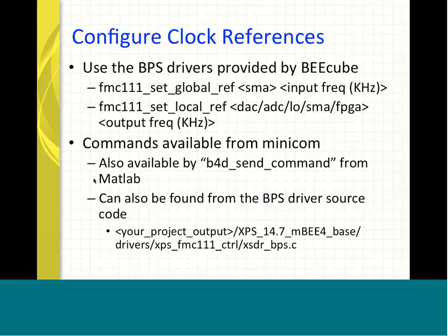As people who have already used the FMC111 or miniBEE SDR know, you can use the B4D send command from MATLAB to change these frequencies. So if you don't want to use minicom, you can use the B4D send command from MATLAB to write a script to change those frequencies.